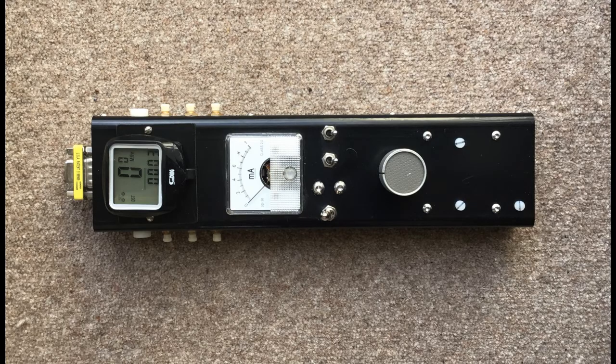We come now to the control strategy. In all these discussions we will consider that demand comes from a rotary potentiometer that sets an input voltage to the electronics. Firstly, we will consider the most basic system, where a single motor in a single loco receives a voltage Vs defined by the demand.